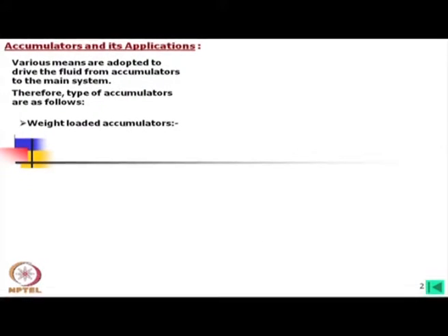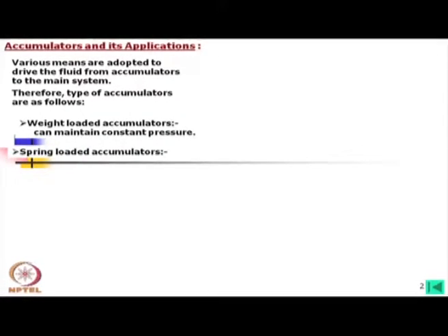Weight loaded accumulators. This has the unique advantage that it can maintain constant pressure. Spring loaded accumulators, where obviously the force reduces when the compressive spring expands. So, therefore, there will be a change in pressure, a variation of pressure. Gas charge accumulators, which are commonly used.